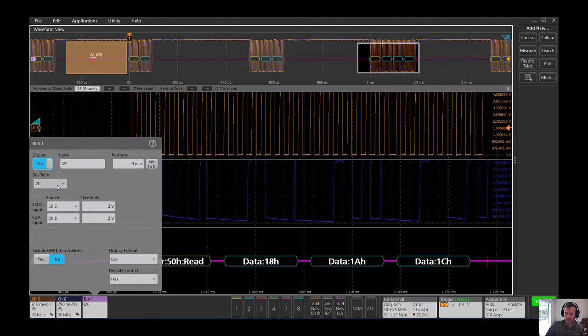Now, I2C was initially selected for us, but we've got lots of different options in here, whether you're working with something automotive like CAN, LIN, FlexRay, something that's more aerospace and defense related, like this MIL-STD, ARINC 429, SpaceWire, or more power related, or NRZ, non-return to zero style. Lots of different options in here, and we're continuing to develop and release more serial bus standards. We can really set this up depending on what our embedded system is doing.